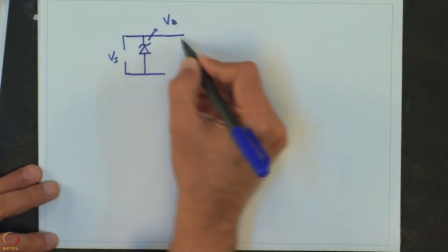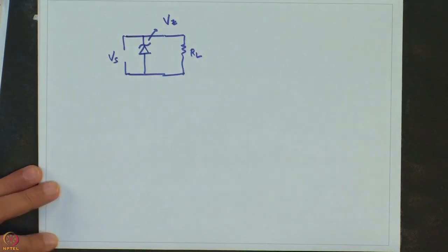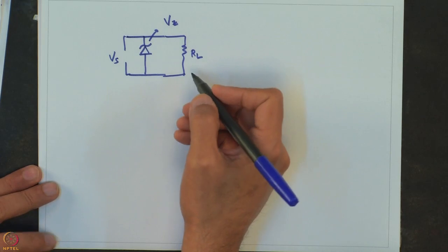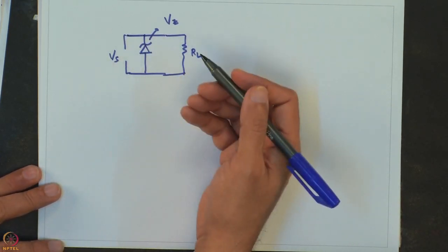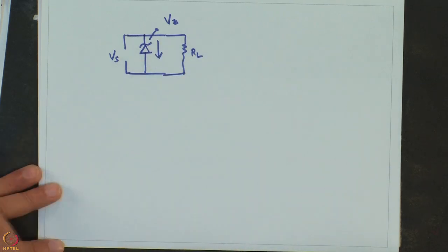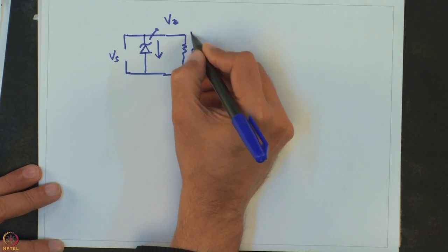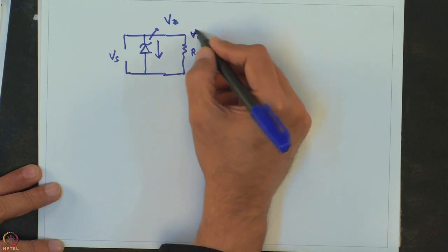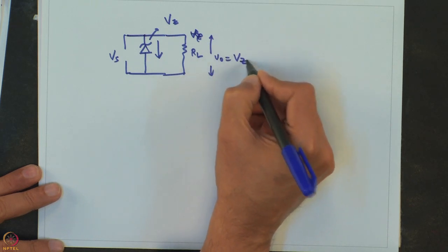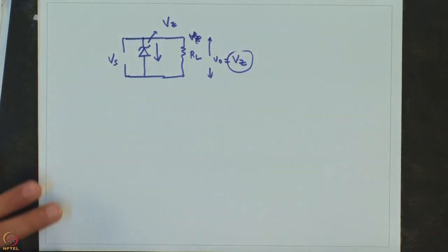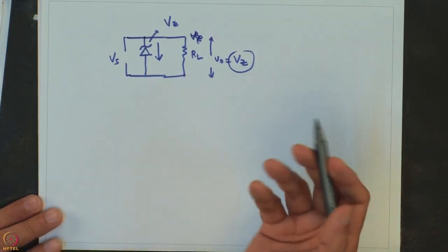Then if I apply my load resistance right across the Zener, we will find that the moment the Vs tries to go beyond a certain value, my Zener diode will break down and hold the value at Vz. So, Vz is what is going to appear across RL, and assuming this is what we want the voltage to be across the load RL, then this will do my job.